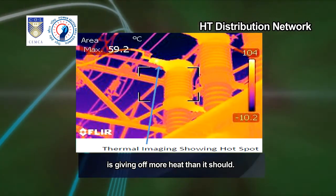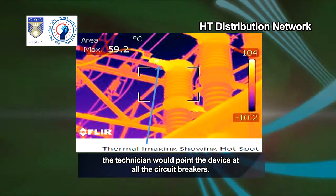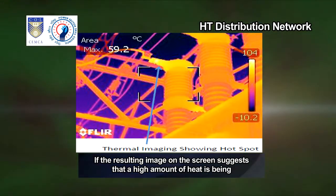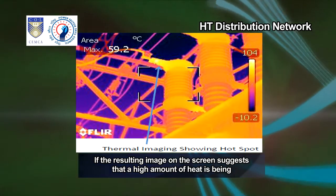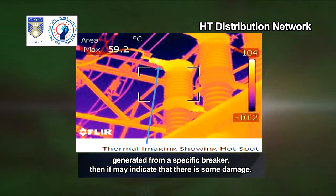than it should. For example, in the case of using a thermal imaging camera for circuit breakers, the technician would point the device at all the circuit breakers. If the resulting image on the screen suggests that a high amount of heat is being generated from a specific breaker, then it may indicate that there is some damage.